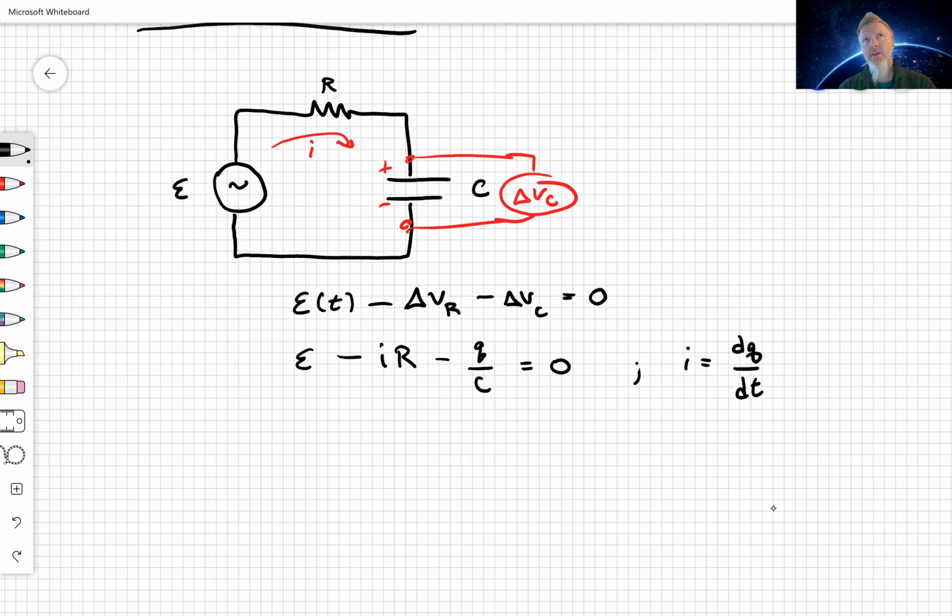So what's happening here physically is the power source is pushing current, say clockwise. That current is hitting the capacitor plate and building up charge on it. The power source is going to slowly lessen its push, but still keep pushing. It's going to push really hard, and then it's going to push less hard and less hard and less hard, and eventually stop pushing. At which point the charge on the capacitor is going to be essentially as big as it could possibly be. Okay.